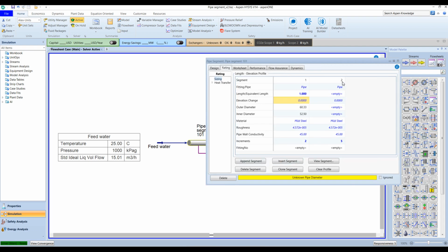You add. Now we've got a segment that is added at the end of that 1 meter pipe, but it's not really a pipe. We want a ball valve. So on the drop down there, you come and get a ball valve fully open. The ball valve, we're assuming it is a full ball valve, which will have the same internal diameter as the pipe. And then you've got a green bar there. That means we have modeled now that 1 meter pipe and a ball valve.